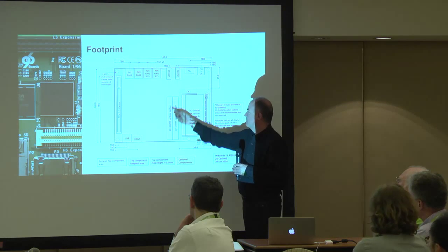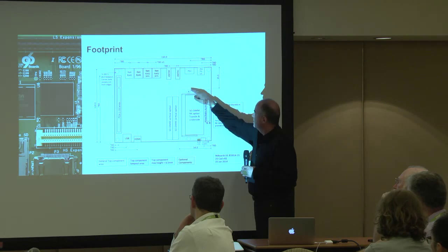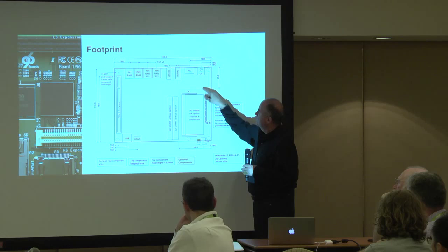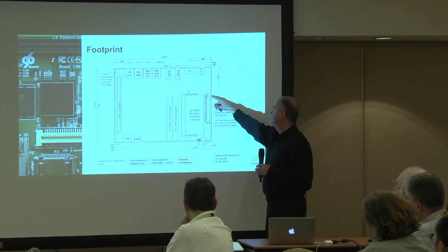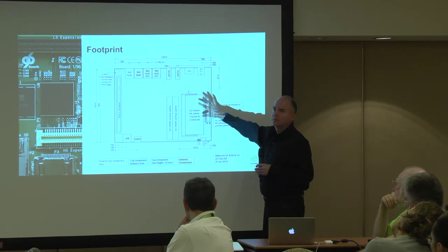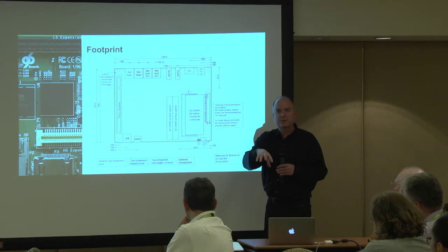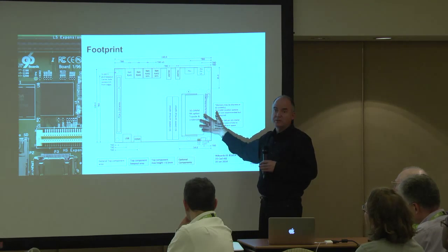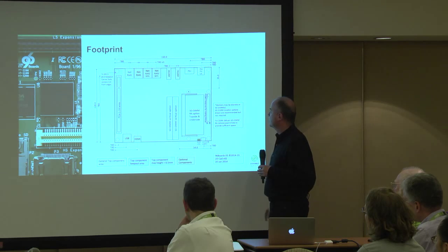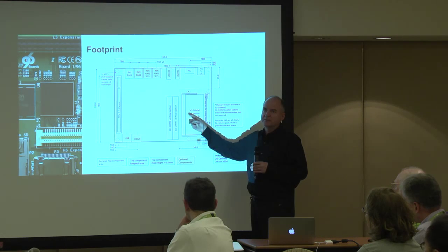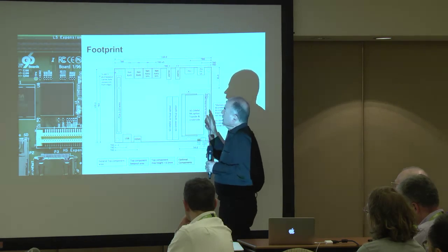Recommendation of SODIMMs, either vertical or horizontal. This is the area where the standard low-speed interface board can go on. So the Arduino board I was talking about earlier that goes onto the consumer version, you can also plug it onto the server version, right, if it's just using the low-speed connector. There's no high-speed connector on this because CSI and DSI you don't really find on server chips.